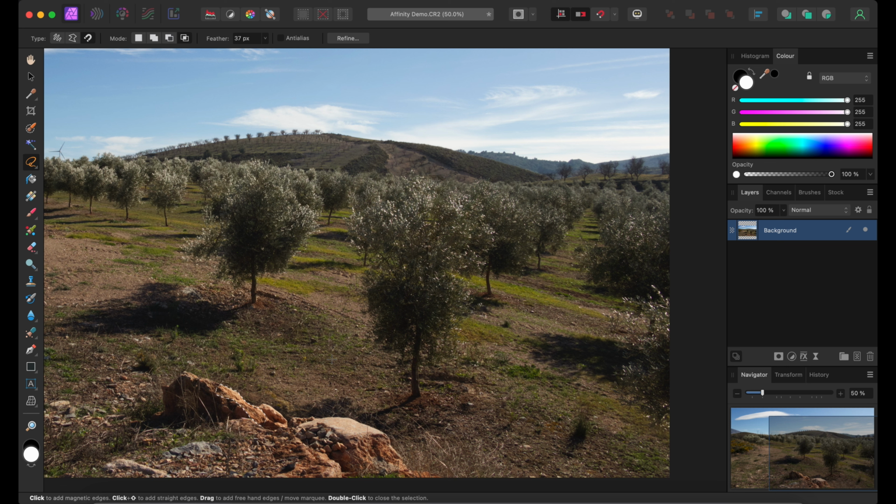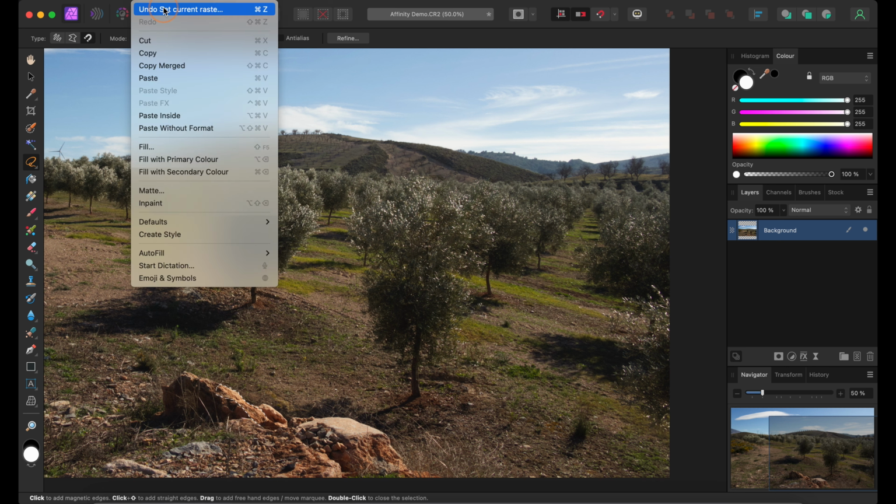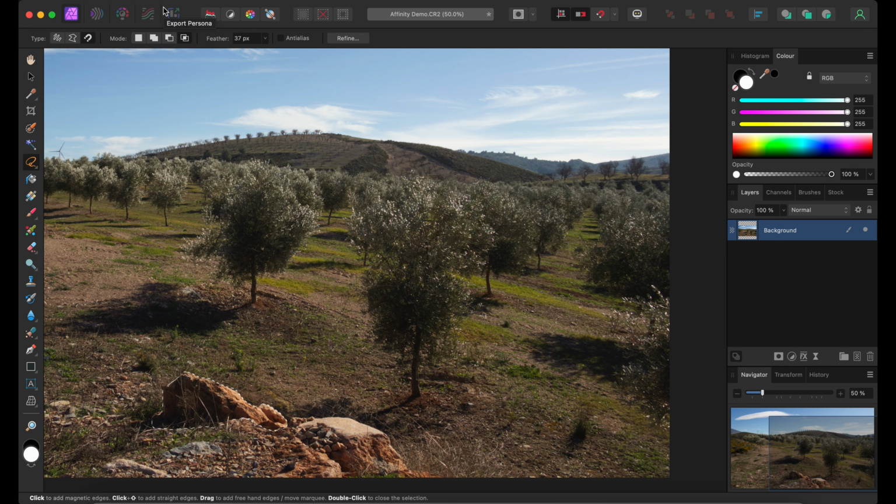Okay, so you can see that this was inside of the first selection. So if we go back here, undo, there's my original selection, and I drew a shape that roughly accommodates that lit up area. And this is a good way of getting at areas that are difficult to draw freehand. Okay, so that's the freehand selection tool.